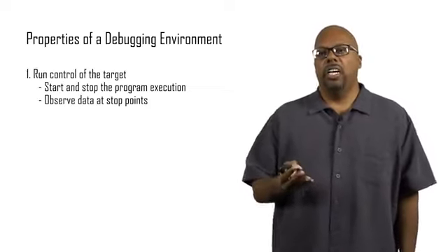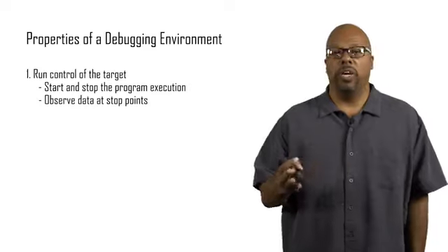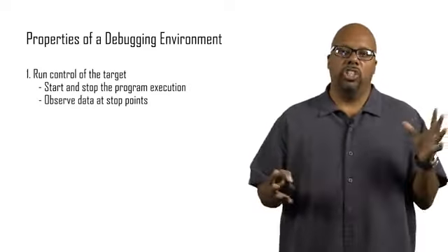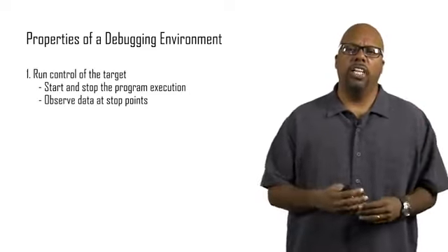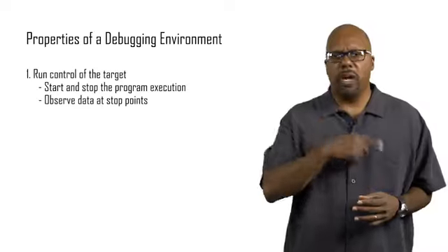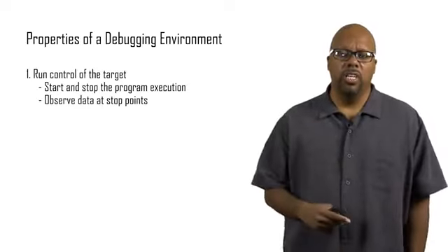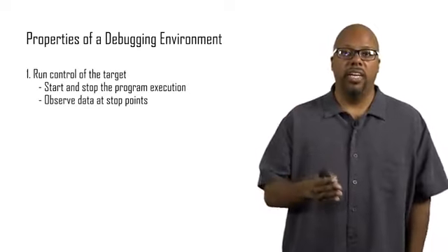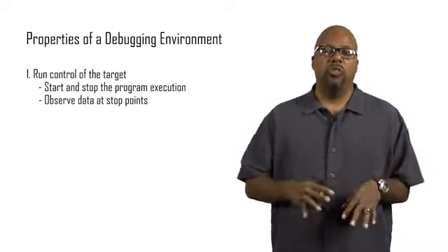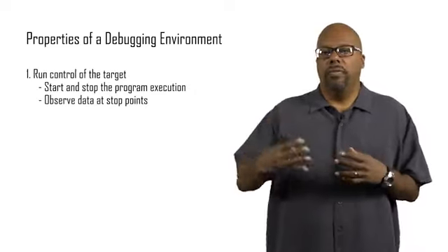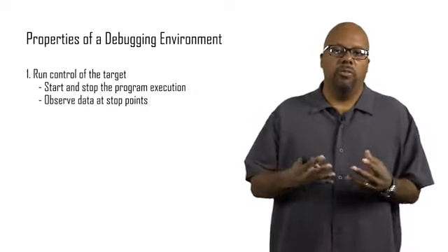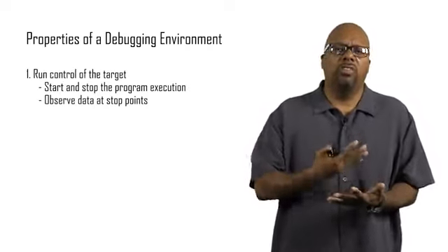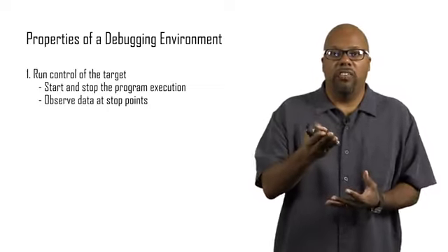Generally this is done using breakpoints. We won't be using breakpoints, but basically you look at your code and you see something's gone wrong and you have a suspicion: "Oh, I think the problem's somewhere around line 53." So you set a breakpoint at line 53 and you let the code run until line 53. Then it stops, and depending on the interface of your debugging environment, you can look at the values of the registers, the memory, and the variables when you're at line 53.